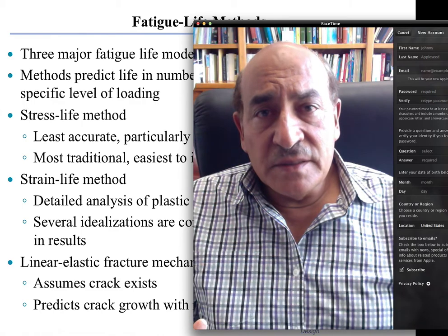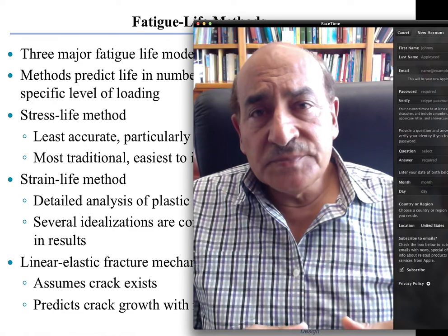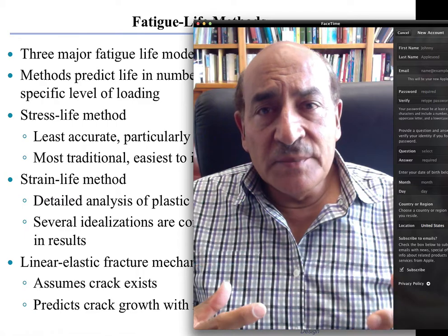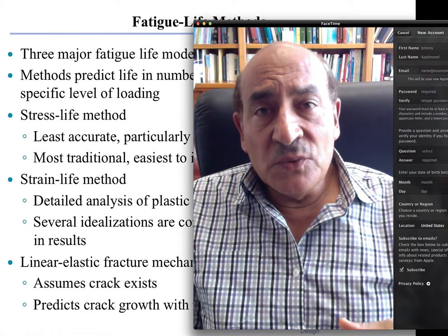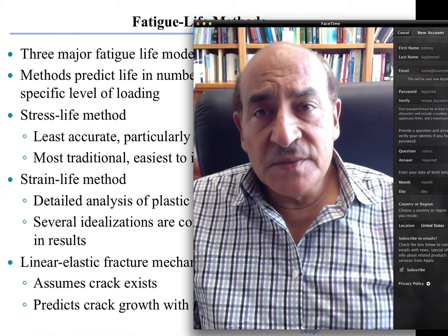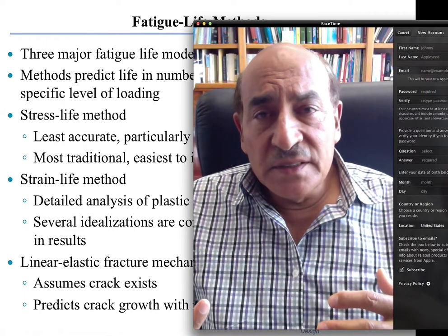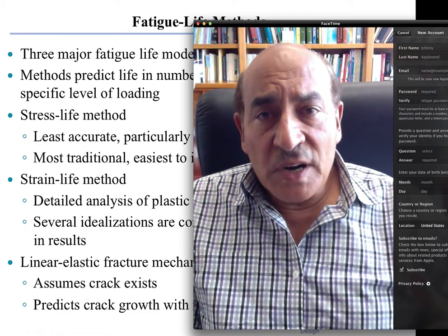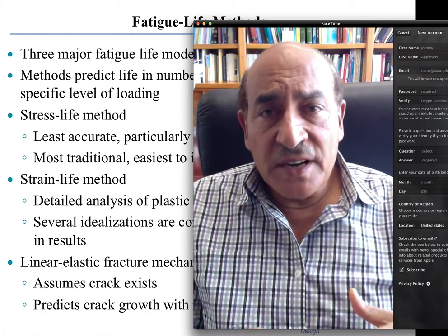If it is partially elastic or brittle, then the eventual failure will be based on exceeding a limit of fracture mechanics. As we've seen before, once we know the crack length and we know the fracture toughness of the material, then there will be only one stress that the material can take before that crack will propagate, once its stress intensity factor is greater than the fracture toughness.